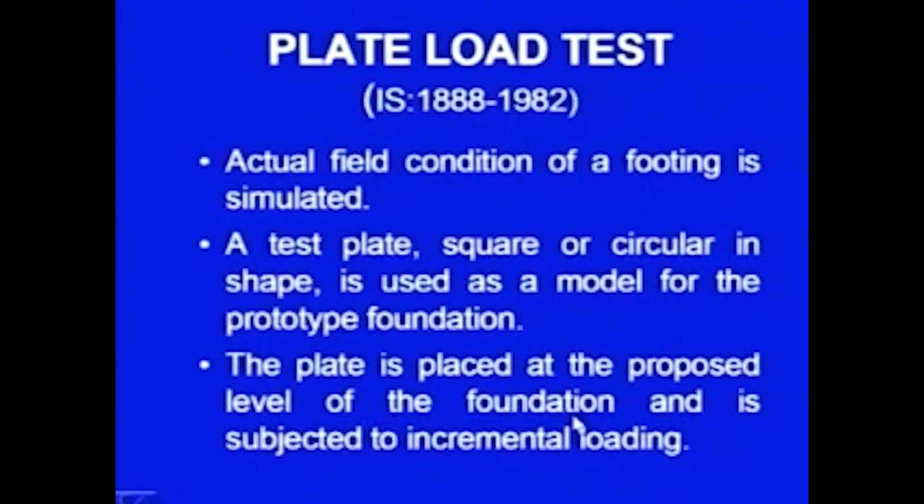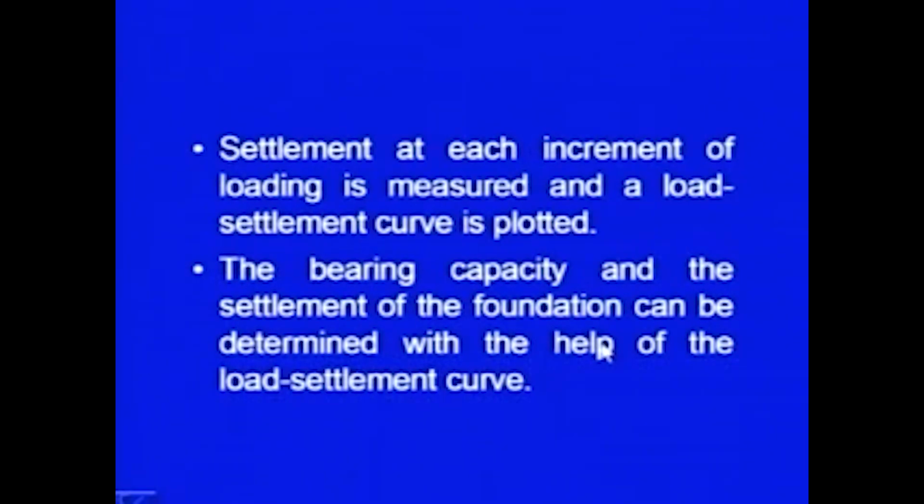We will be using a test plate which will be simulating the foundation, and the plate is placed at the proposed level of the foundation. Wherever the foundation is proposed to be kept, this plate is placed at that level, and then it is subjected to incremental loading. Like in case of actual foundations also, the foundations get incremental loading as the construction proceeds, the loading increases. Then settlement at each increment of loading is measured, and a load settlement curve is plotted. So, this is the basic thing.